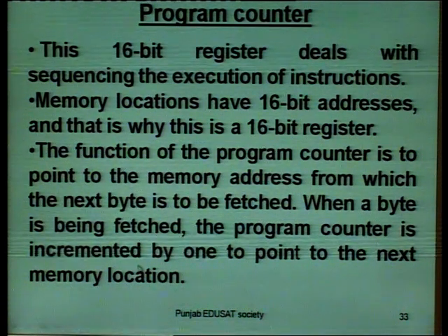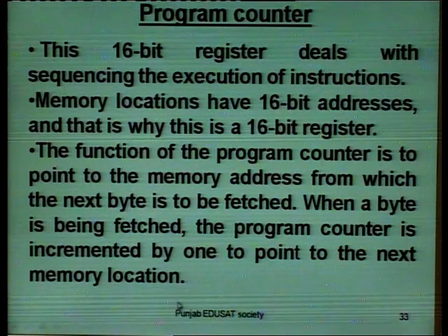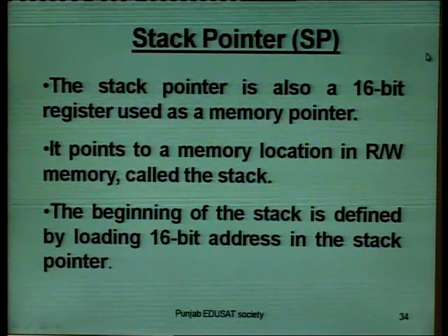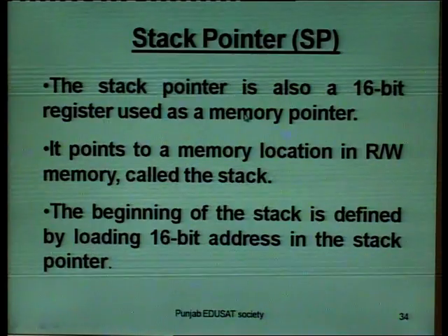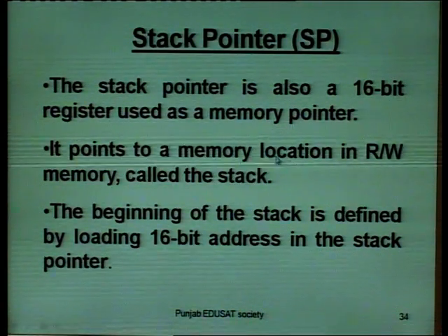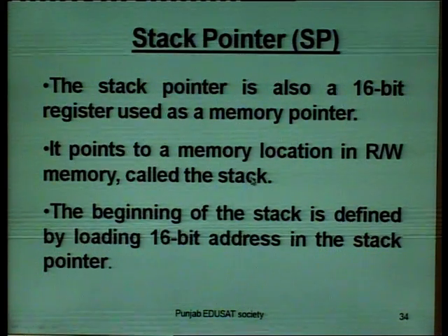Program counter is incremented by 1 to point to the next memory location. Then we have stack pointer. Stack pointer is also a 16-bit register used as memory pointer. It points to a memory location in read-write memory called the stack.